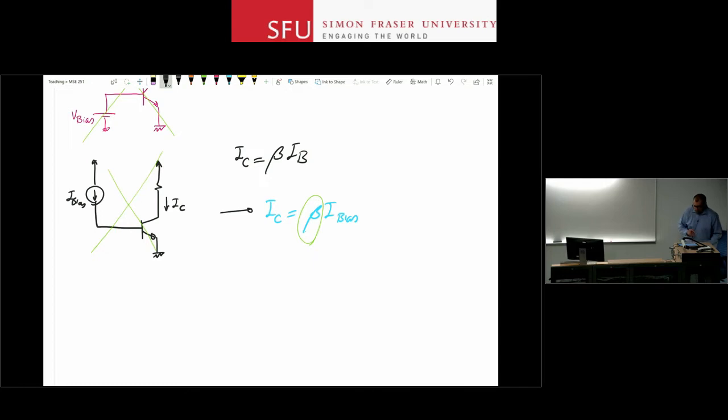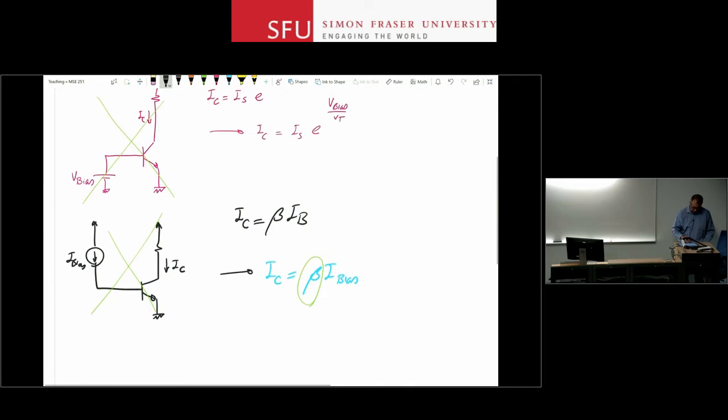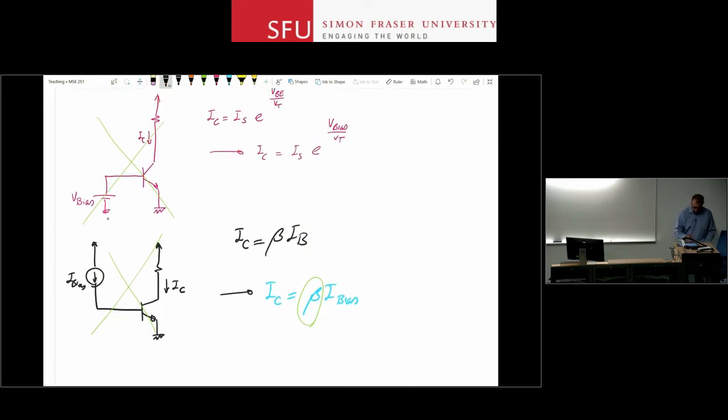Before moving to the next section, let's just go back and think for a second about how I can realize a desired bias voltage here or a desired current here. And the solution in both cases is based on using resistors. You have resistors, you almost have total control on resistor values. You use resistors or resistor combinations to realize what you need.